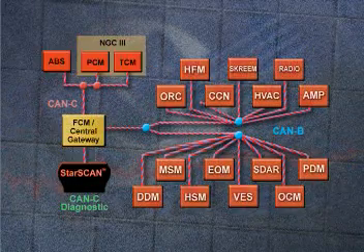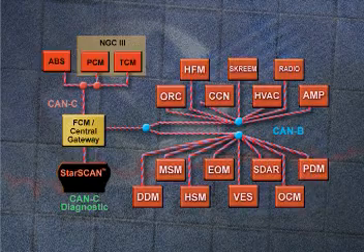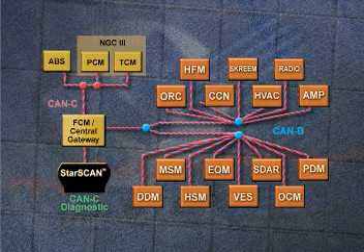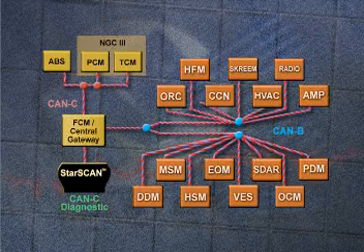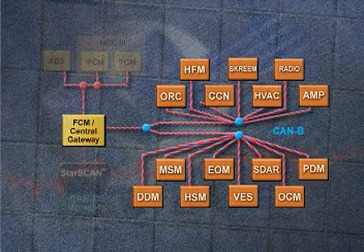The central gateway controller on Durango has a number of jobs to do. For one thing, it separates the 3 buses so that they can operate at different speeds. Because of the separation that the central gateway provides, parts of the network can continue to operate even when other parts may not be operating.